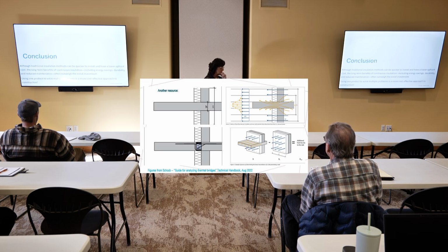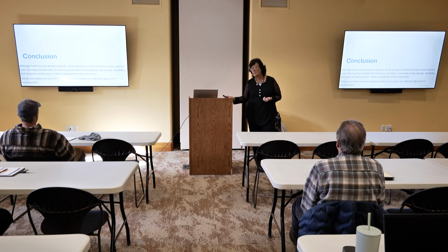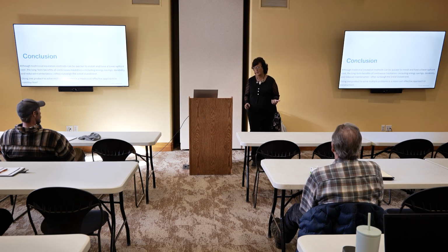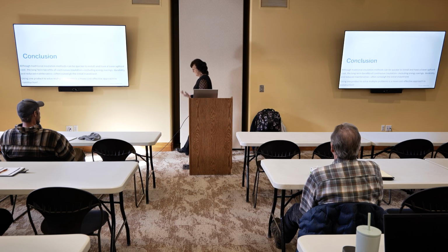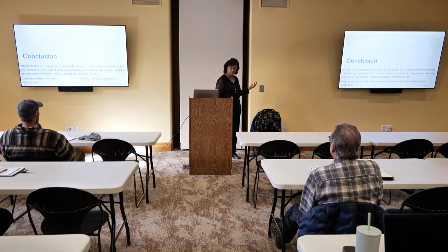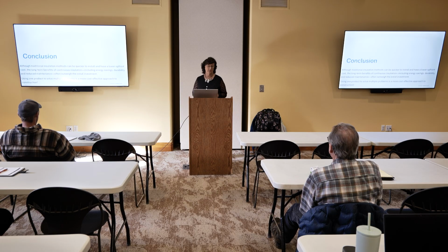All right, continuous insulation, yes, it's more expensive, but is it really? If it could take the place of a few different products, it's all one install, and you don't have several different installers, you don't have several different products. Adding just the right amount will save on your moisture issues. Doing the right kind is going to help you with your wildfire issues. So I think it's one of those things that we're just going to have to get used to, this continuous insulation idea. So lots of different things to consider, one product to solve the problems.